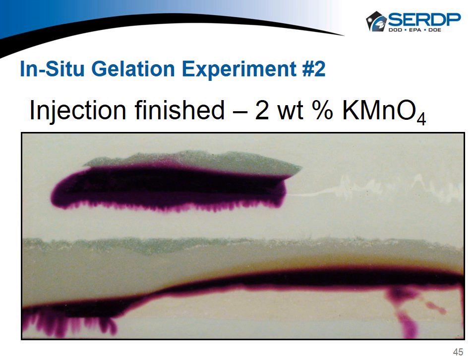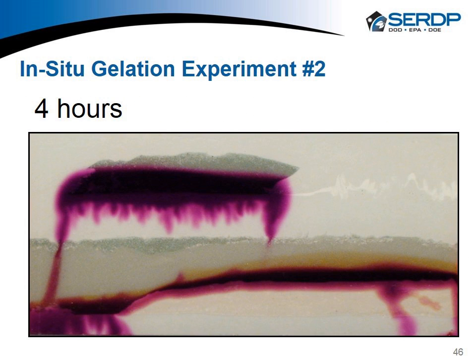And the next slide shows the situation after 4 hours. There's a bigger oxidation rim and greater diffusion into the clay lens here, and here the solution is gelled at this point in the coarse lens and at the coarse layer, and you see the development of strong instabilities and the sinking of the potassium permanganate rich dense solutions towards the high conductivity lens in the middle.